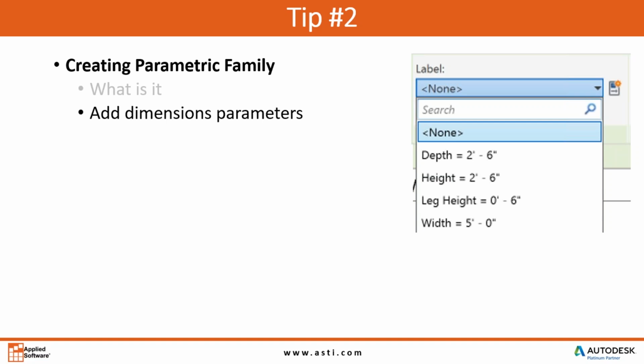So those dimensions, those out to out, for example, those are saying I'm grabbing the edge of either the model or reference planes, depending on how you want to create it. Reference planes are kind of good. That would allow us to then adjust the size of that model.